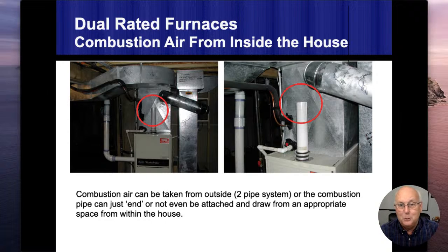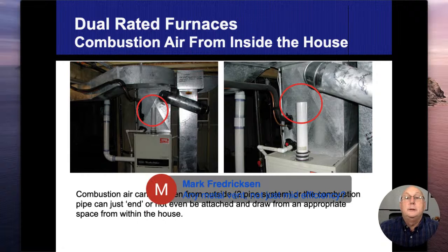Can't be in a bedroom, can't be in a bathroom, can't draw that combustion air from the bedroom or the bathroom. It needs to be big enough, depending on the BTUs that are there, to get enough combustion air. And quite frankly, now I'm taking conditioned air and bringing that to the outside. Let's see what this is here. So any metal vent, not just mid efficiency.